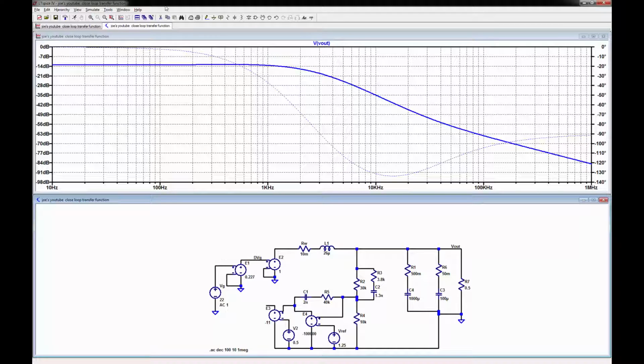There it is. And you can see if we add 1 over 1 plus T, 1 over 1 plus T comes this way. Remember, we're at 30 kilohertz. We're at 30 kilohertz right in here. 10, 20, 30. That's why it opens this up to come up. And this is going down by a factor of 2. That's why you come up, you come down, and you have what you have for loop gain. So let's look at that closed loop again. We come back over here, and we put the circuit back. So we look at that again one more time.